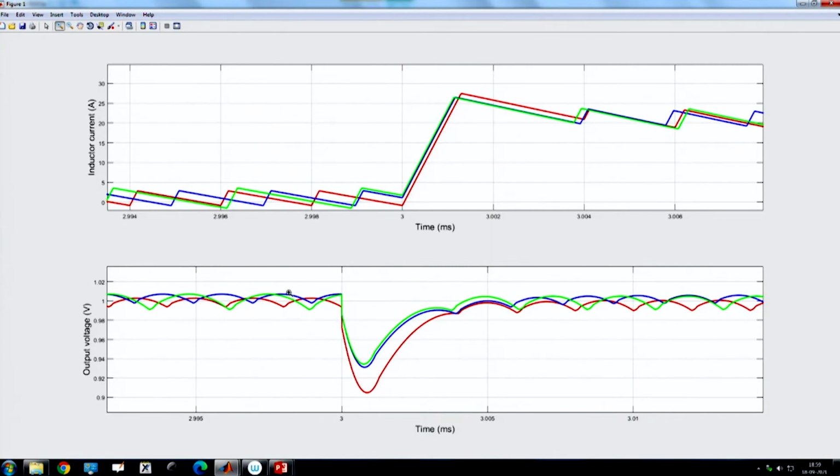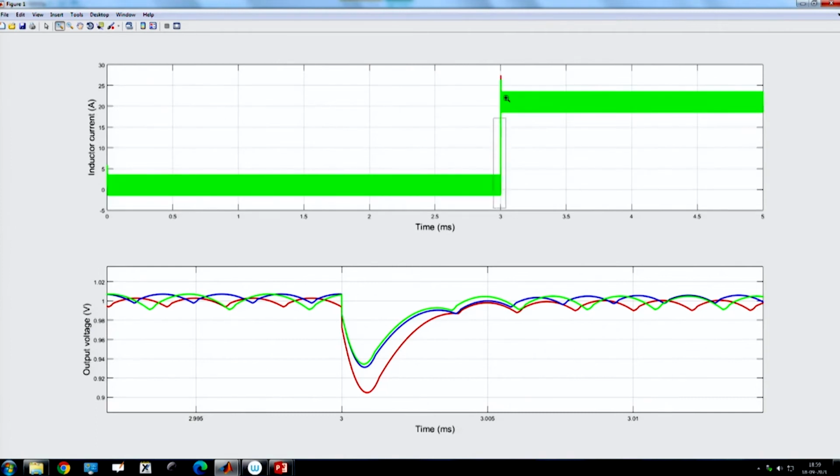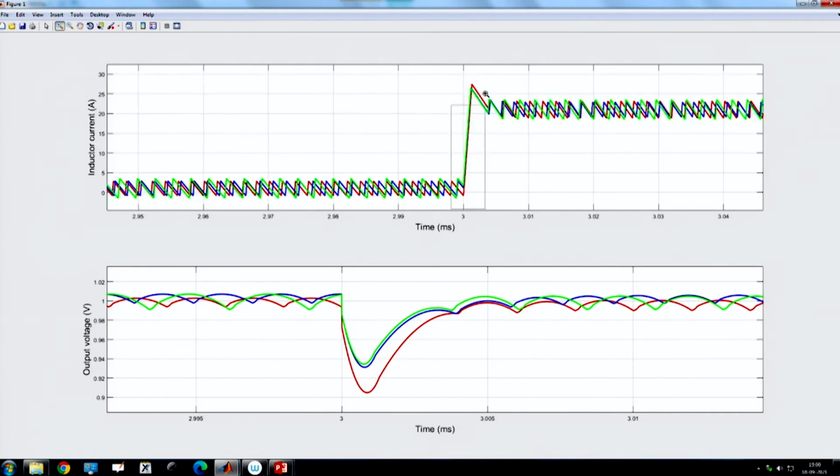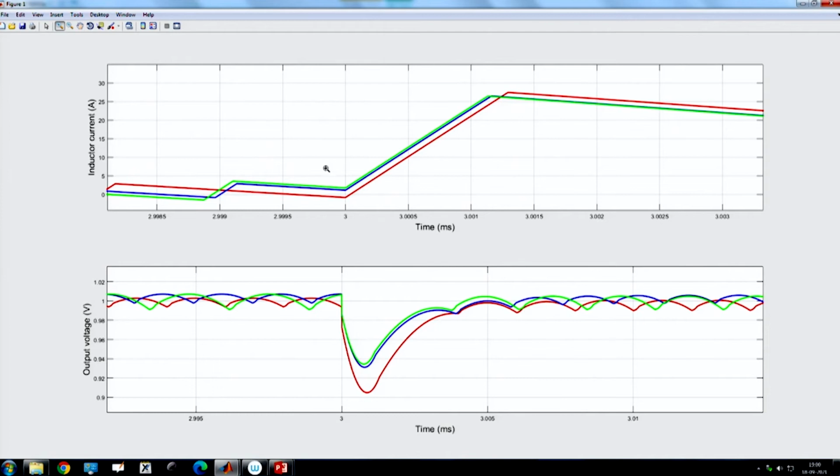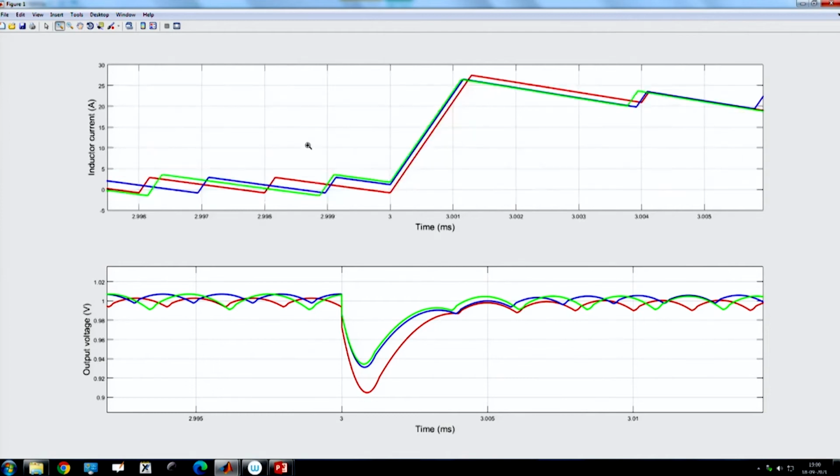Just a minute, yeah. Because there can be slight delay in the PWM based control that we did because of the modulator delay, but in case of switching surface based hysteresis sliding surface based design, there will be no delay, it will respond because it is a hysteresis control.